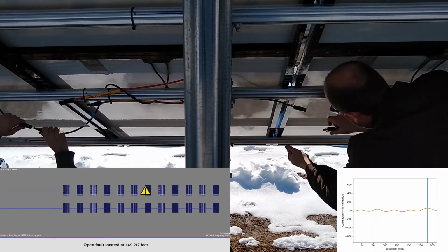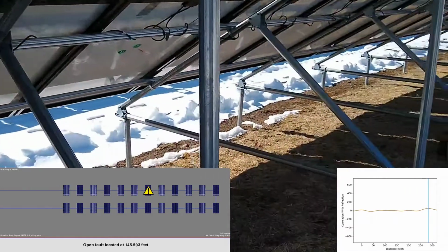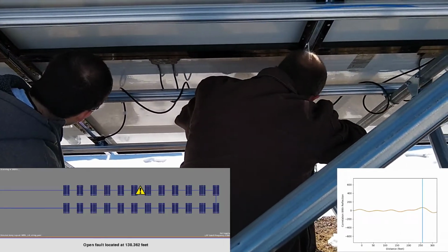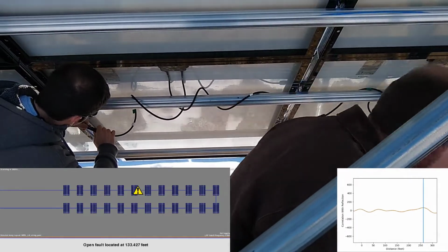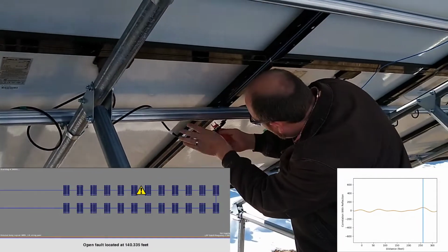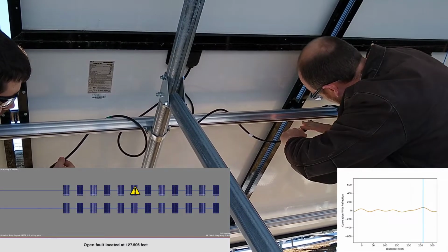It is worth noting again that our device measures from both directions, and we demonstrate this by having the technicians move down the other side of the loop and get closer to the SSTDR device. Faults appear closer and closer to the SSTDR as technicians move up the loop. The accuracy is still spotty up until the first 2 panels are reached.